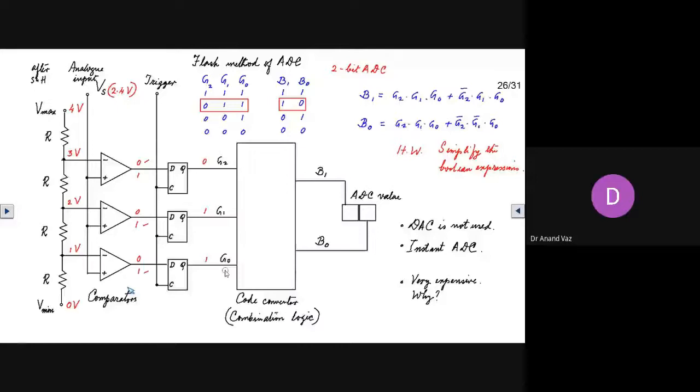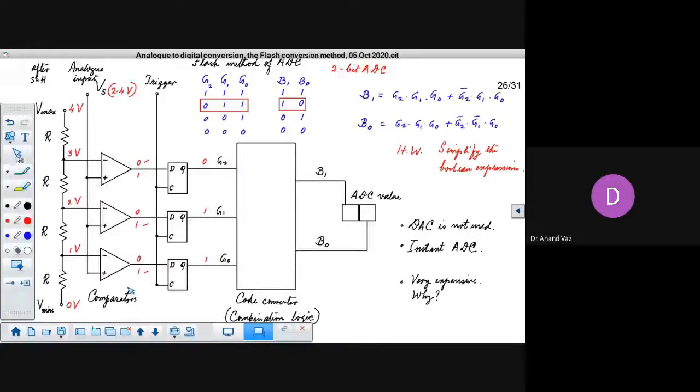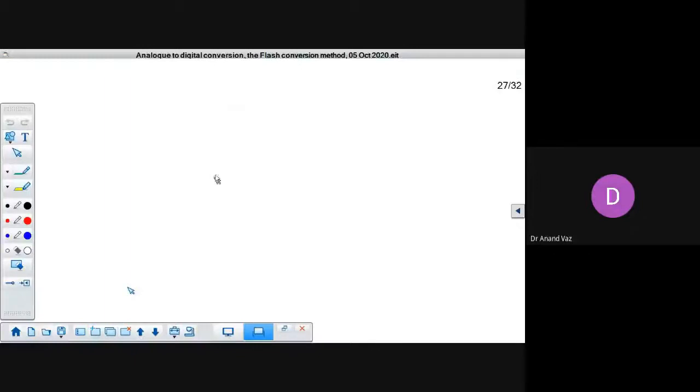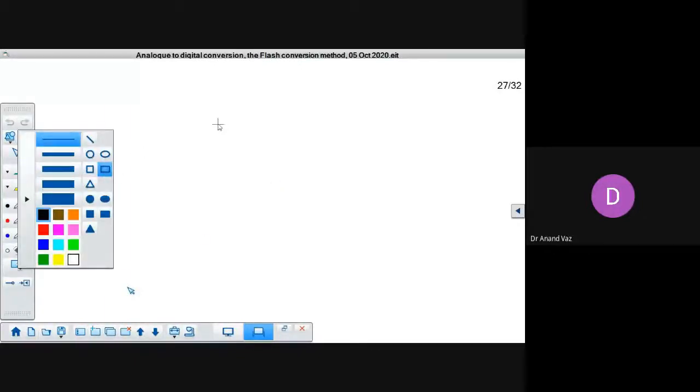Now, because this is very expensive, you can certainly simplify its usage. You can use it in a particular combination. You can multiplex it with different sensors or with different channels and use just one analog to digital converter. Okay, so for example, you may have a multiplexer circuit.